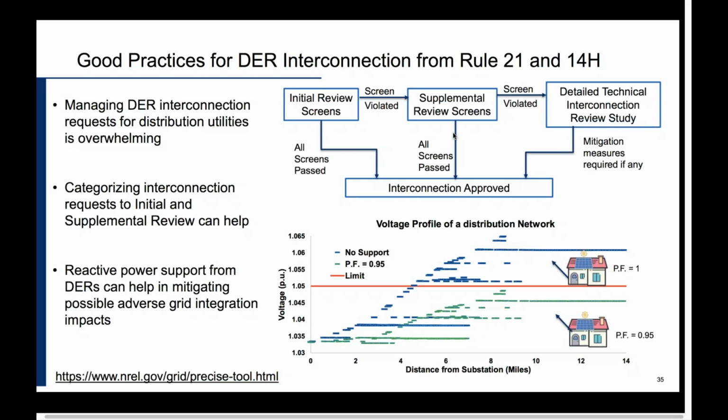So as long as it's not well organized, it becomes a big burden and very hard to pass through. And more than that, as the advanced inverter or all these 1547 standards come in, just along with saying yes to interconnection requests, the requirement here is to also use the technology and make benefit out of it. That means if I say I want reactive power support from these DERs, it's also important to have a way to optimally identify them and use them.